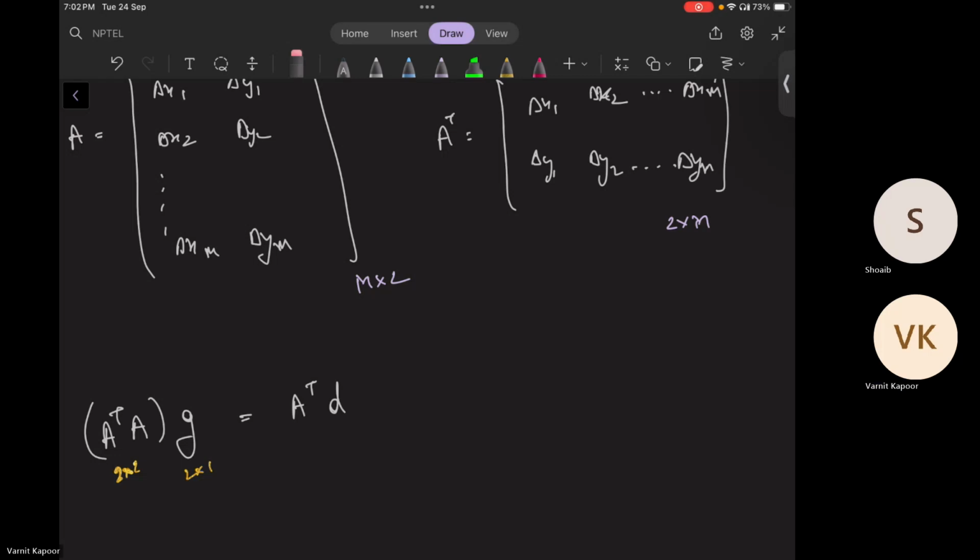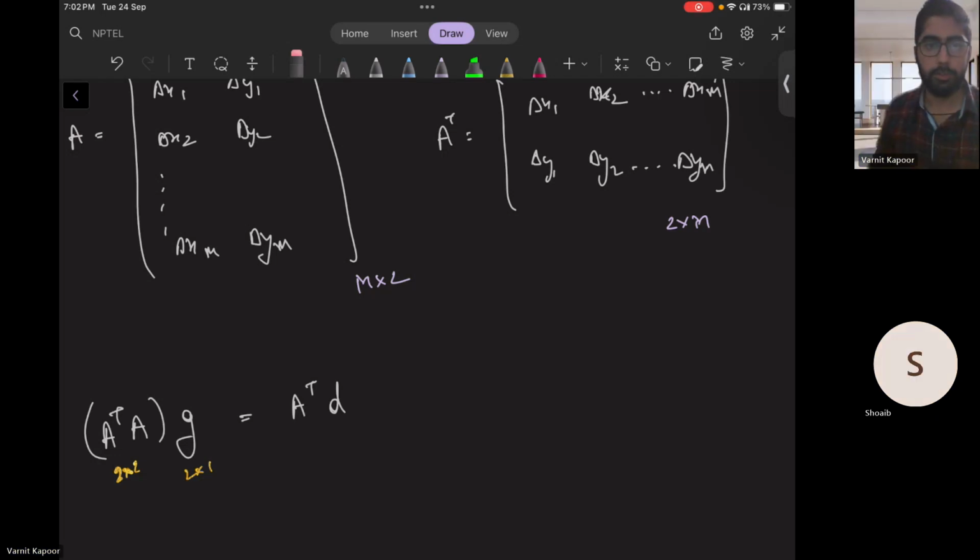Okay, let's start the next topic. So far we discussed the gradient calculation methods, the Green Gauss method and the least square approach. Now we'll start with secondary gradient influence on the coefficients and implementation of unstructured solution algorithms. Up till now, we have been saying that only the secondary gradients make the solution possibly not bounded, that the guarantee that the solution is bounded is taken away if you have secondary gradients. But we have not actually proved this or looked at why it happens. So that is one thing we are going to see today.